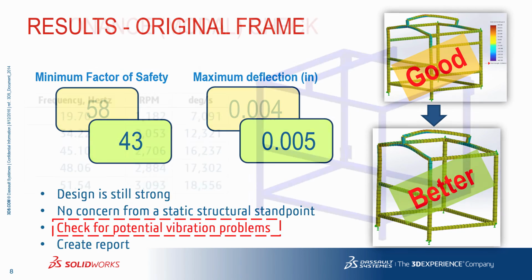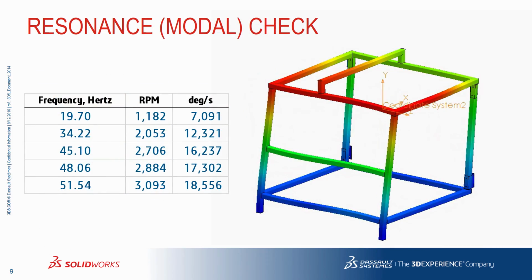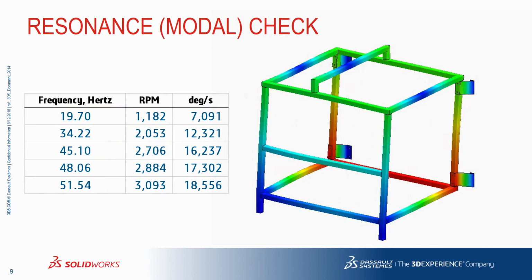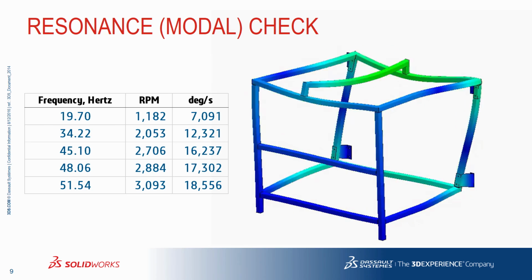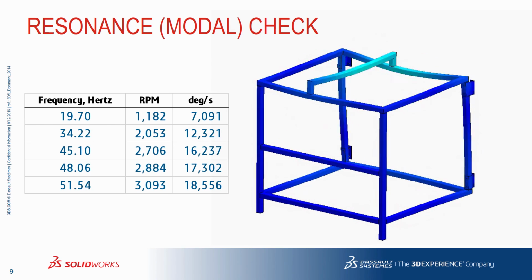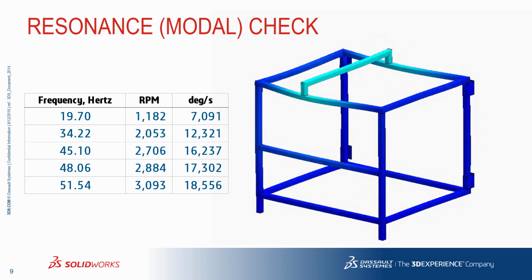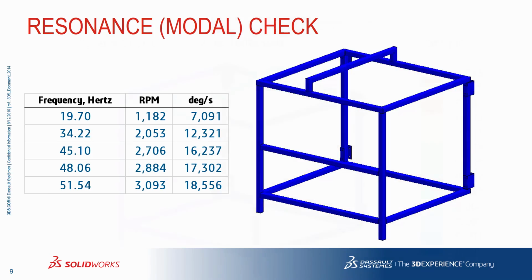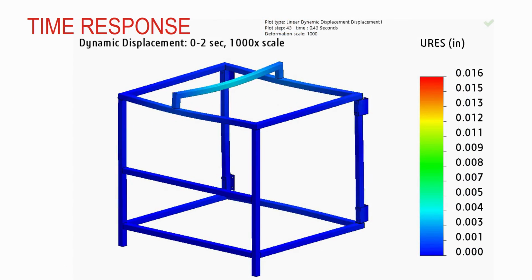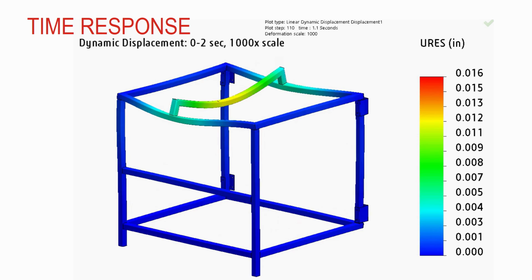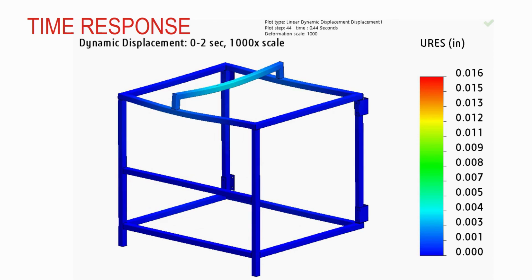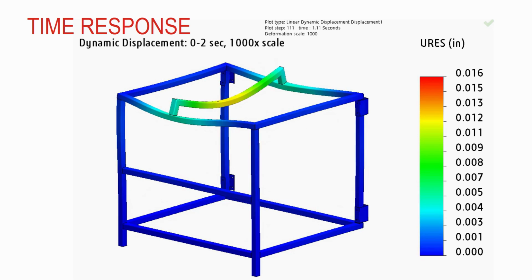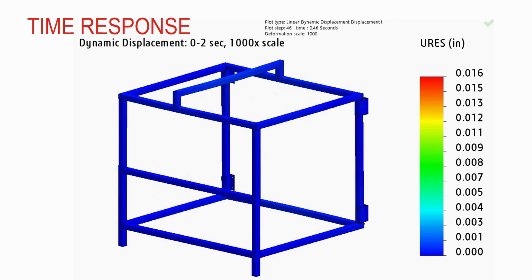But when I start to get more towards validation and maybe looking at potential vibration analysis at the end of my design cycle, well, then I really want to have shells because it gives me that extra level of detail. For example, the brackets in the back, how do they really fasten with the bolts to the next part of the frame, and really being able to visualize what the response looks like. So one of the things we had to do in this analysis was do a time response. And you can do this with beams, but again, here I get a real clear picture of both the load path as well as the bending stress on the top and bottom of that weldment piece.